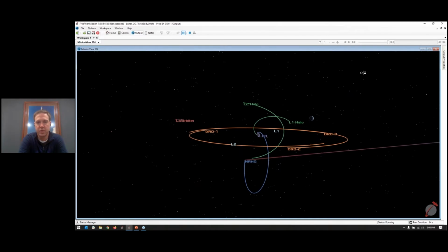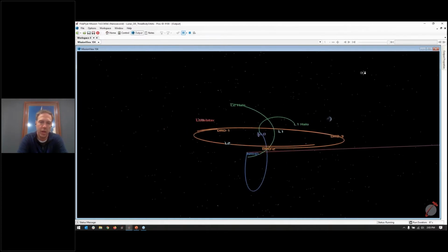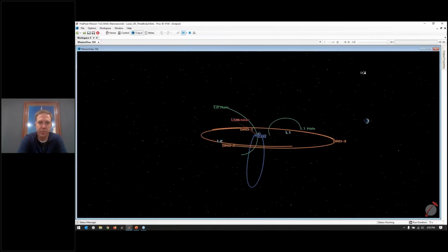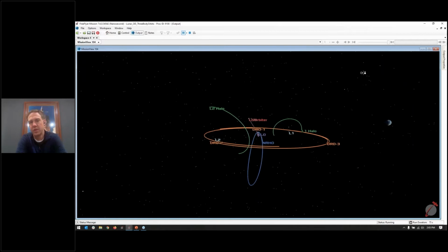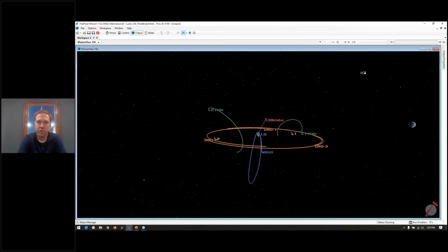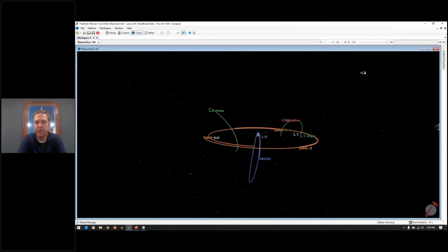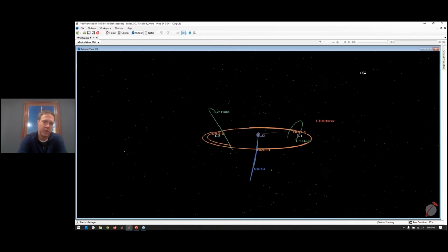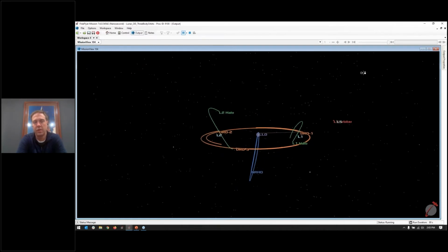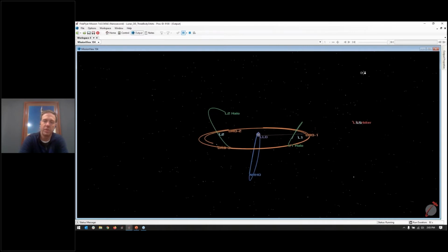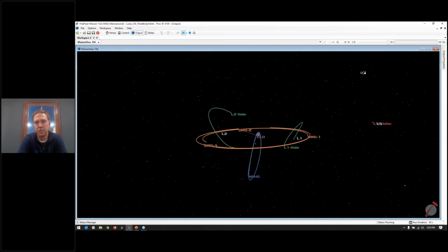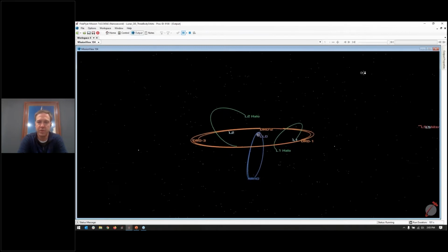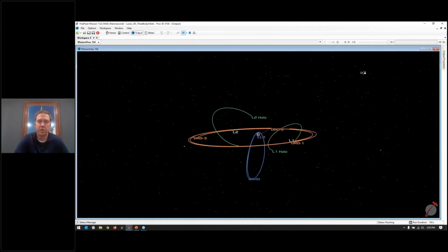The design space can be wide open, and you can do trades on relative geometry, tracking schedule, availability, and you can see in this video, I'm showing link contacts between various pairings of satellites in all these orbits. The distance associated with the link and the amount of time any particular link may be available are all things you can and should consider when designing a navigation constellation or any sort of constellation in cislunar space.